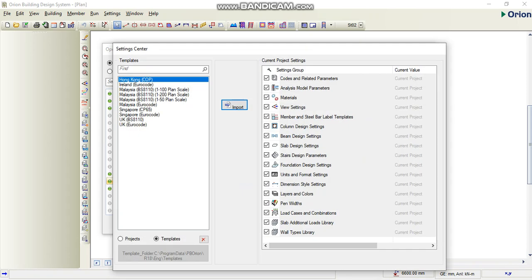Okay. Then you're going to select the template. Select the design code type that you intend to use, which are all standards practiced globally. But here in my own country, Nigeria, where I'm taking this training from, we apply UK standard in our design.